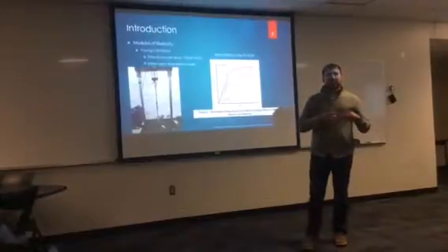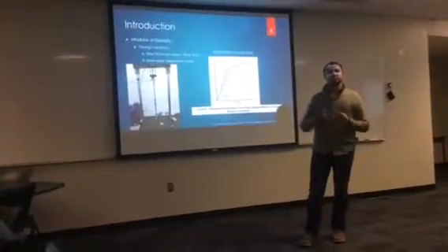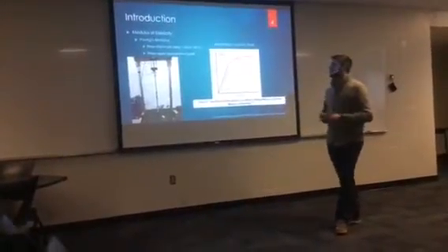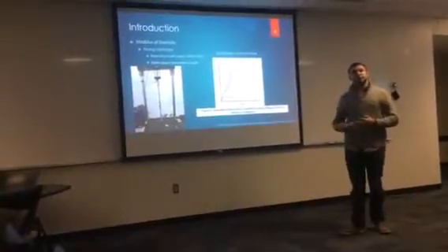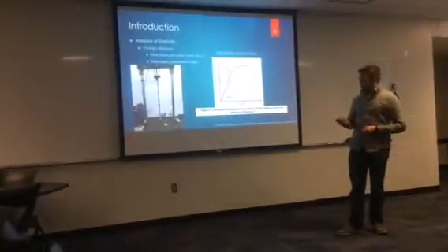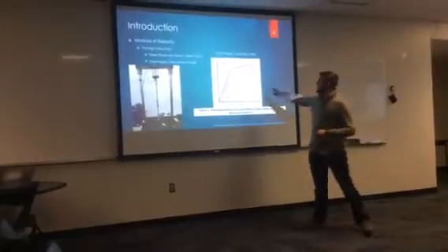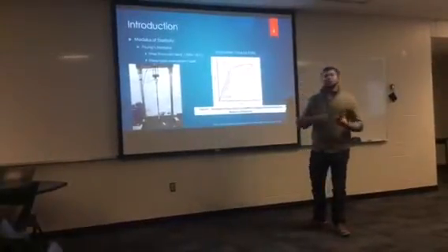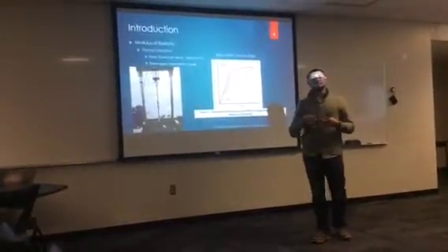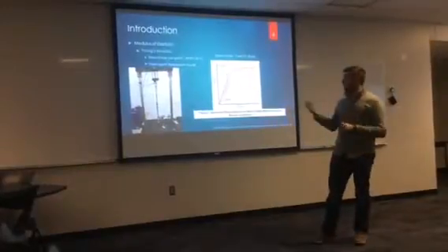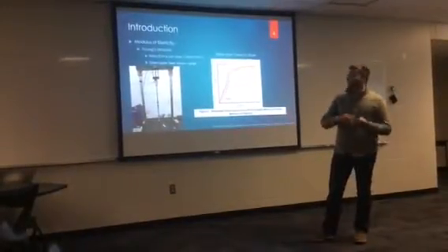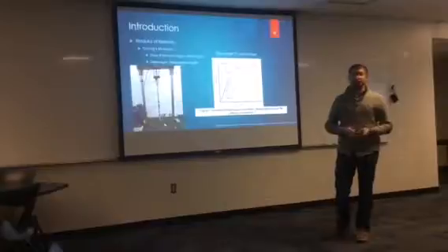It's essentially a material's resistance to being deformed. It's also called Young's modulus. The modulus is calculated by taking data from a stress-strain curve, which is shown here in this figure. And a stress-strain curve is generated by taking a sample and loading it into a load frame, here an ADMET eXpert, and then pulling on it at a set displacement rate.